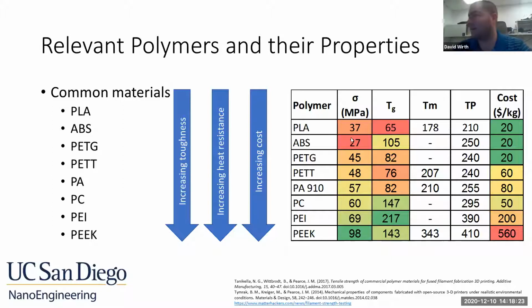So as I said, if you leave PLA in a hot car, it can deform, right? That's a big drawback with PLA: it cannot tolerate high temperatures. If you want to 3D print an electronics enclosure, you probably don't want to choose PLA if the components inside are getting hot, right? Because you could melt your enclosure. So you want to use something like ABS or nylon or PETG.